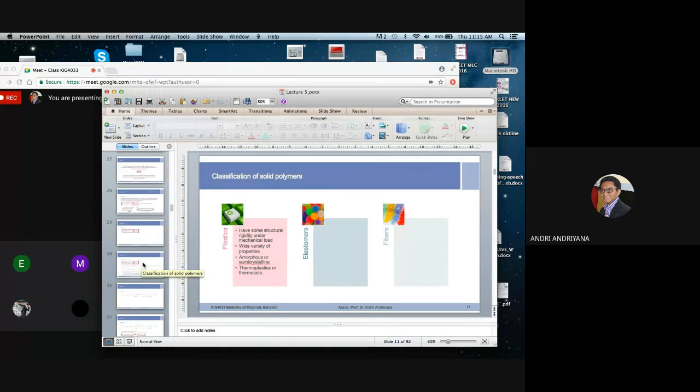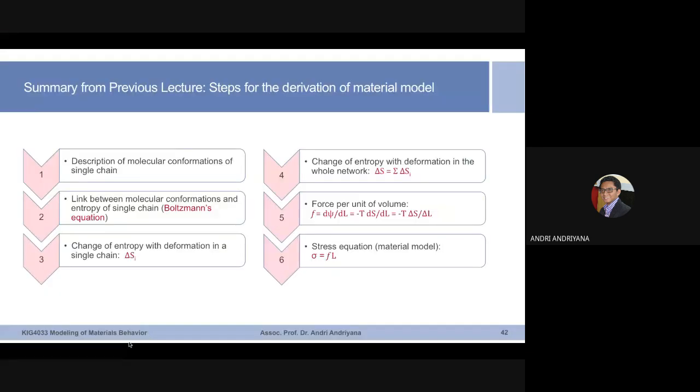Again, I will not go much into the detail of the statistical mechanics. So with these assumptions, it leads us to the expressions of the Neo-Hookean model, where we have the expressions of the free energy associated with the Neo-Hookean model. Noting that for the special case where the deformations occur at constant temperature, which is the focus of our work, the free energy and the strain energy have the same meaning.